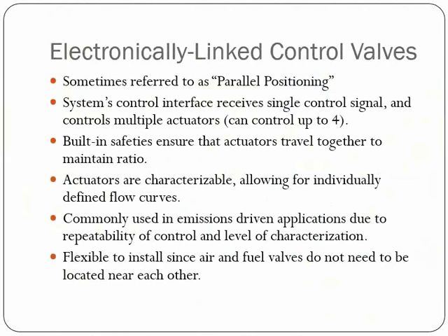With this electronic linkage, these systems need to make sure that the actuators are traveling together, right? The ratio regulators with the impulse line, and the mechanically linked control valves with the linkage arms, ensure that the air and the fuel travel together. But with electronically linked valves, there's no physical connection between them except for the wiring.